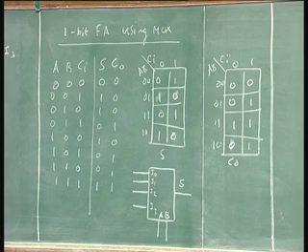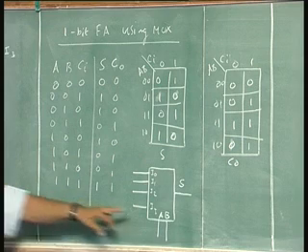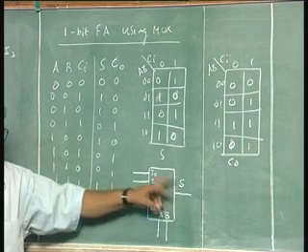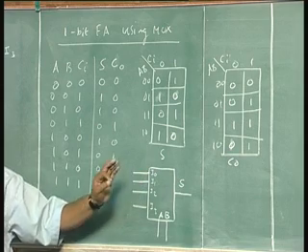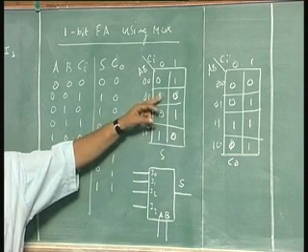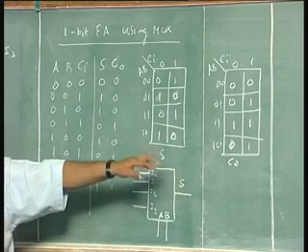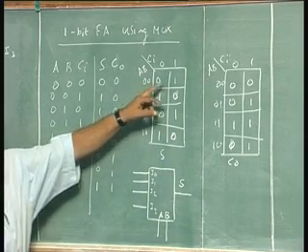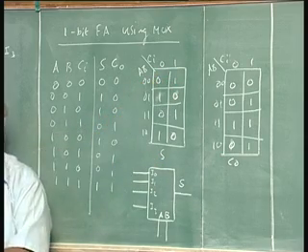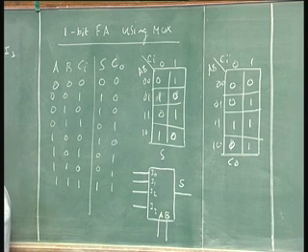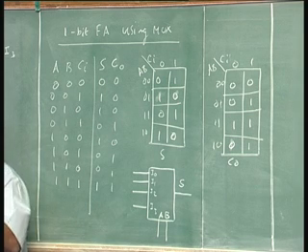or from whatever here, when AB is 0, 0, which is S1 S0 is 0, 0, output S is connected to I0. So, if I make I0 what is required according to this Karnaugh map, then that will be implemented. So, when AB is 0, 0, sum should be same as Ci, sum should be 0 if Ci is 0, sum should be 1 if Ci is 1.